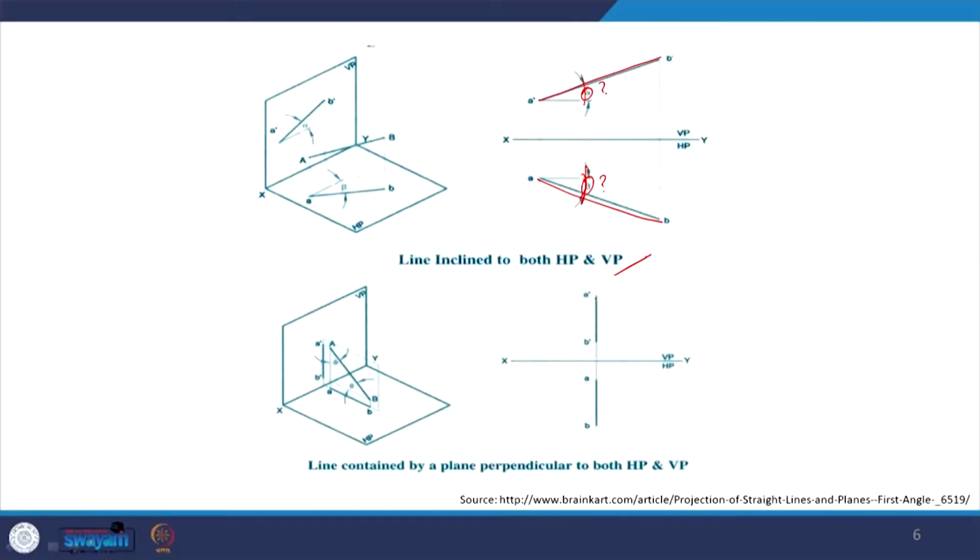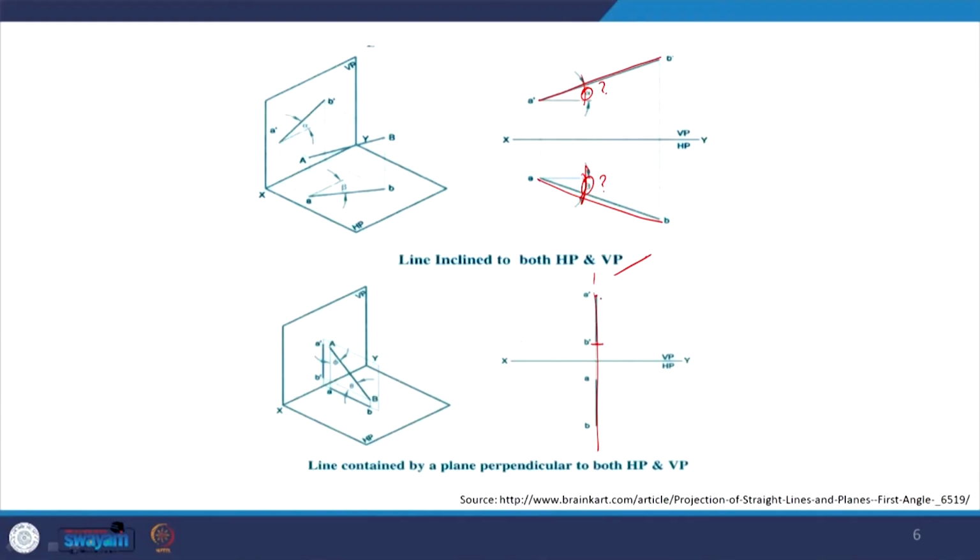In this case, which is a special case, we will be seeing only two straight lines in one single line. There will be just one projection because the plane in which the line lies is perpendicular to the HP as well as VP. So, we will be seeing diminished lengths, greatly reduced, and we will not be seeing any angle or any true length of the line in the final picture.